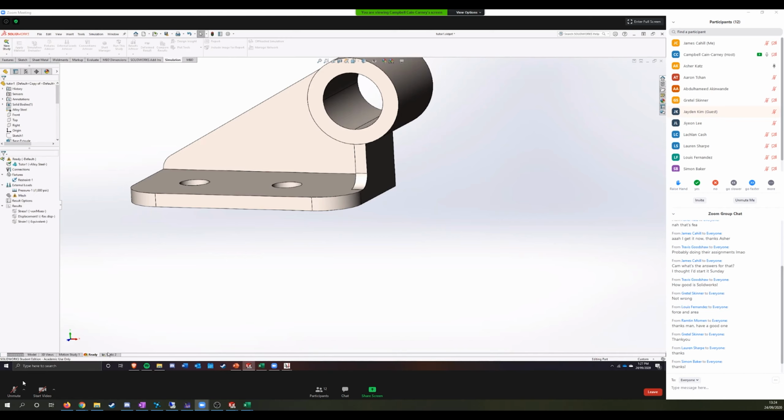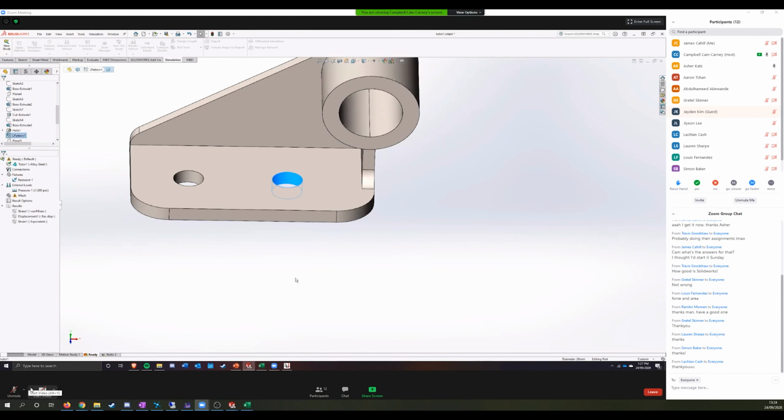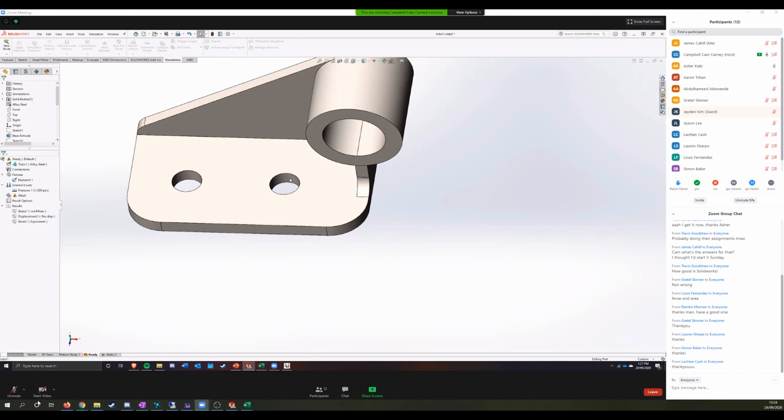Alright, so Campbell, would you fillet the holes as well? Because that was getting a high stress as well. No, so that's getting a high stress because you fix this face and then it's trying to push down through the part. So that is